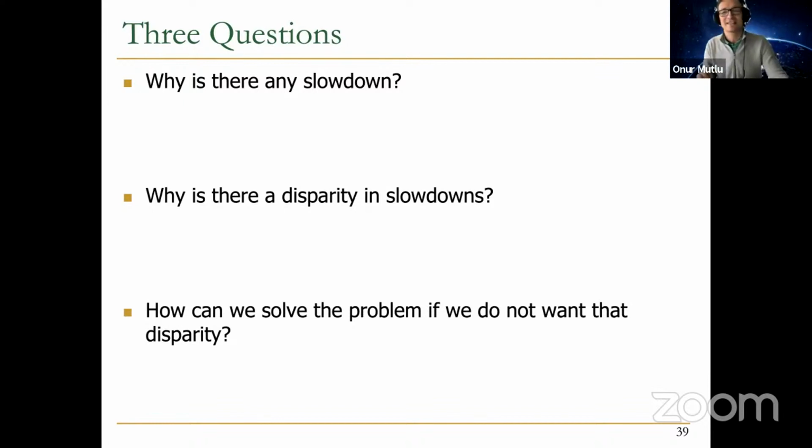So modern systems, what they do is, when they figure out that the system is getting close to a thermal emergency, let's say, if it's running at a temperature that is considered too high, that it would potentially break down the system, modern systems do automatic throttling of workloads such that they slow the workloads, like slow the clock frequency and reduce the voltage of a core.